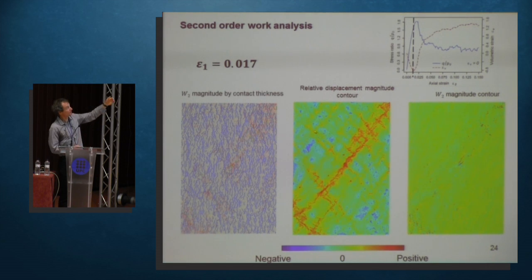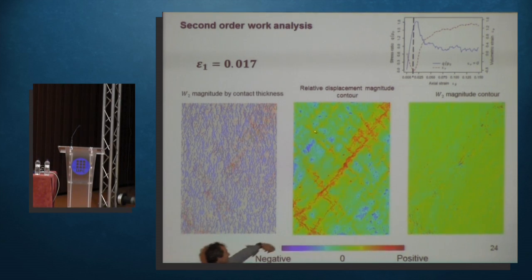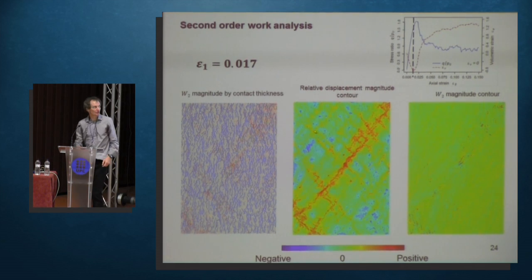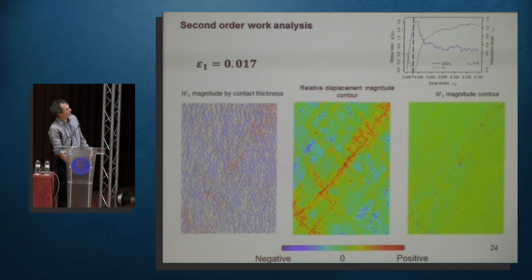So we consider exactly the same biaxial test shown previously, and using an initial dense specimen, you can conceive that we may have a strain localization near the peak or just after the peak. This is what we have obtained. You can observe on this slide a very nice strain localization, and what we are going to plot is a distribution of the local second order work.